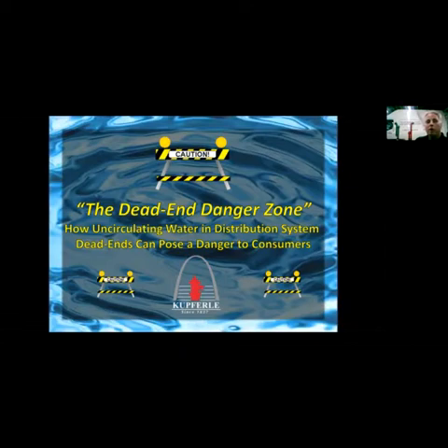We'll briefly talk about the reasons why people flush water lines. When I first got in this business years ago, I thought, why do they flush water lines? Water's water. But as we've talked about before, when you add chlorine to water and you chemically change it and that water ages, bad things happen. Especially on dead end mains and distribution systems where the water is not recirculating with the rest of the system. And if you don't have enough connections on that line, houses or businesses that are turning the line over, that's where we get some stagnant water issues and these dead end danger zone situations.